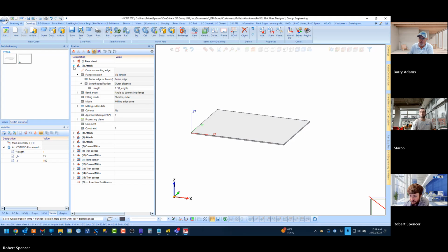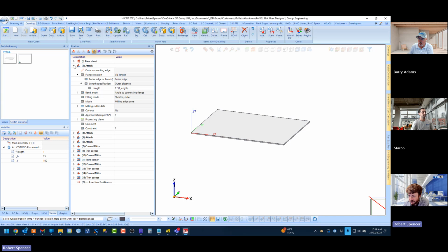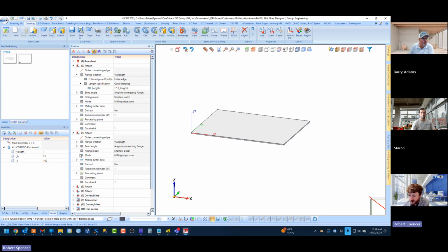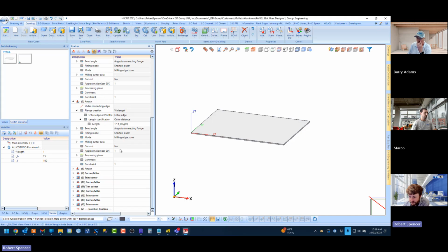Right. So my suggestion would be, let's keep this simple, but let's still add a little bit of meat to it here. Let's just put a variable for flange length in for all 4 of these flanges. And next step here is that we're going to use this panel on an elevation here so you can sort of start to see how it all works together.